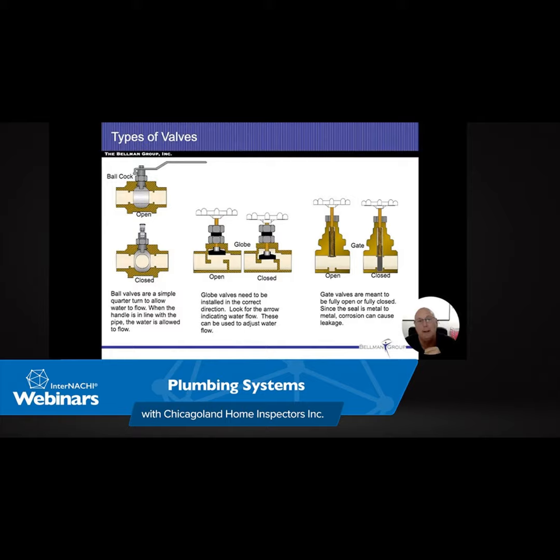Same thing with them touching on the outside. All right, so if I have a copper pipe being held up with a steel nail or resting on steel ductwork that comes in there, just by touching those two metals like that causes the electrolysis to happen. And the weaker of the two metals is the one that's going to start being corroded. In this case, I think it ends up being the steel, or no, it's the copper. But it doesn't matter. We're looking for all the corrosion, changing of colors and so forth when it happens, and we want to avoid any sort of leakage. Now, the cure of this, again, is simple, all right?